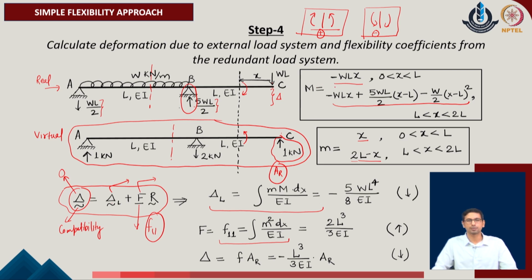But as the support C is a spring support, it will also undergo some amount of deformation, and to know that amount of deformation in the given system, we must consider that the deformation corresponds to the identified flexibility of the given spring member. If the force being considered as the redundant value A_r acts here, the equal and opposite force will also be transferred to the spring system, and this will make the spring move downward, which will generate the reaction of A_r, the redundant value, in this member.